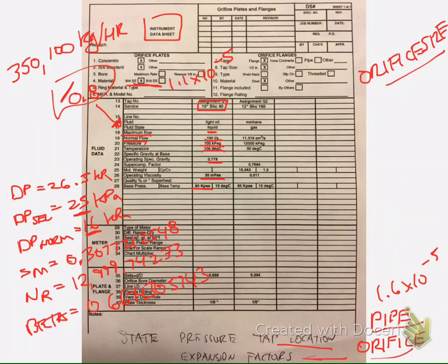So enter 100 degrees C because it's asking for units of Celsius, and then it asks you if it's a liquid or gas. And on this side here, we're dealing with a liquid. It's light oil. So enter 1 in for it to say yes to that, and then it gives me a C value equals